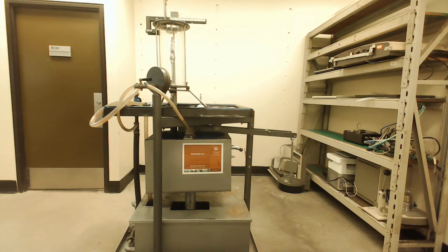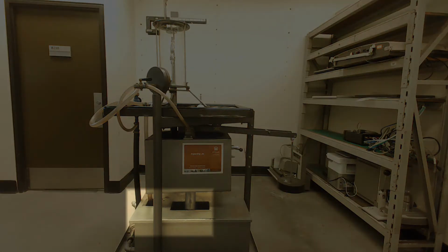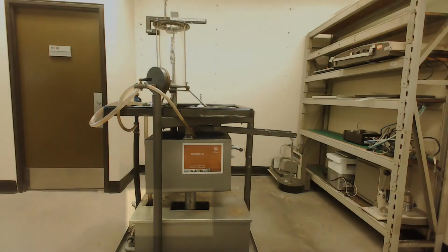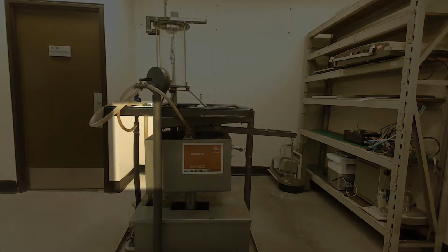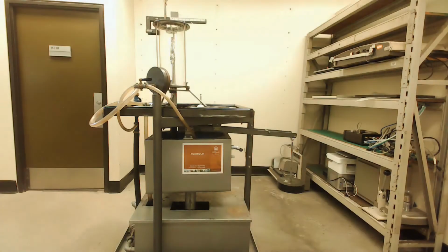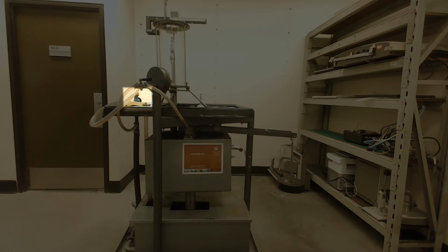As seen in class, the conservation of momentum equation will be used to predict the force of the jet of water. The apparatus, as shown on screen, has the following key components. A pump, located at the rear of the rig, is used to produce water flow for the experiment. The pump feeds up into the rig where it reaches a valve. This valve, when open, will let water flow into the nozzle. Adjusting the valve also enables us to control the flow rate of the system.